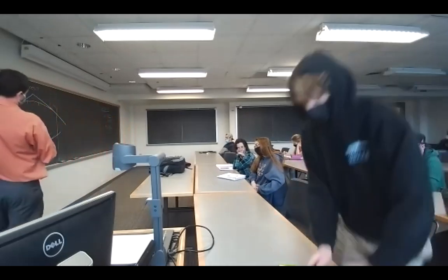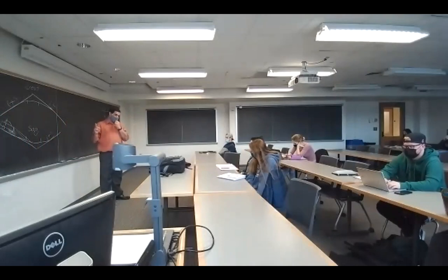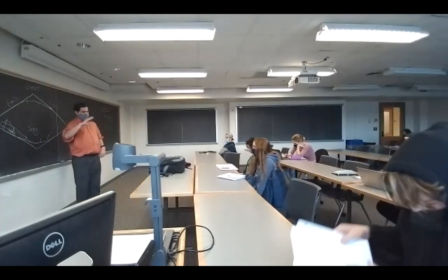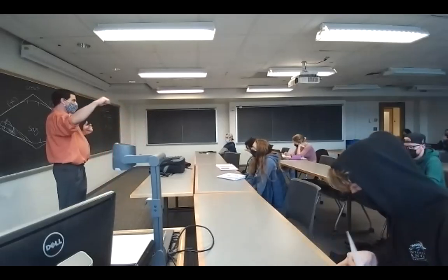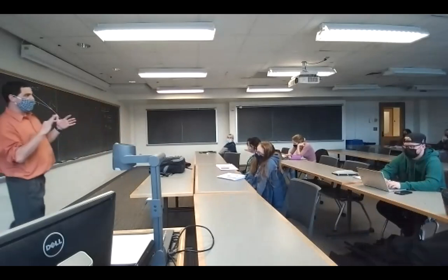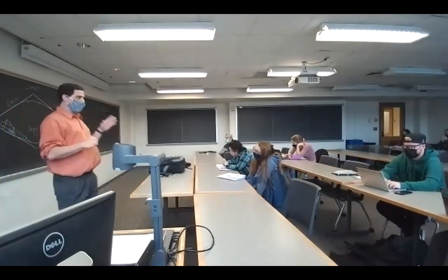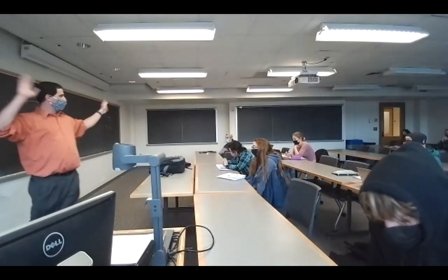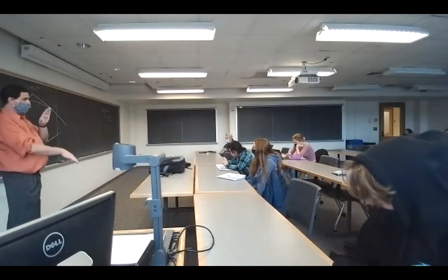So let's talk about how the software does. But before I do that, I want to take one step back. It's easy to think that, okay, I've got a horizontal layout for my road, and I've got a beginning of curve and end of curve. Does your horizontal curve and vertical curve have to coincide at the same position? They're completely independent. Don't try and link a horizontal curve and a vertical. They're not related to one another at all. The vertical curve is just how you transition grades from one to another.